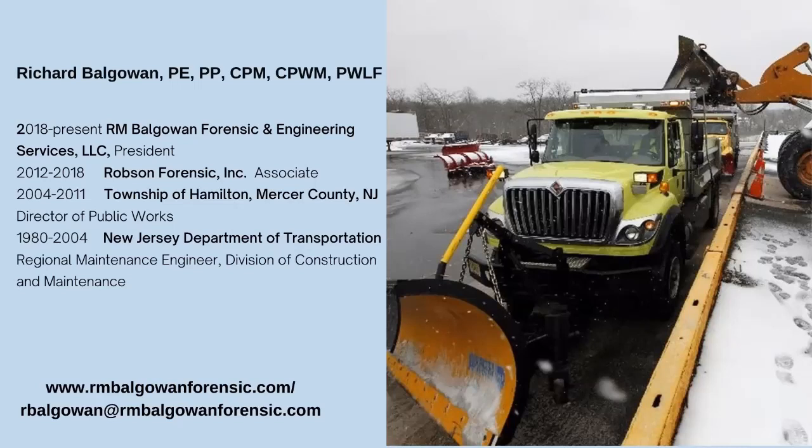So back in the 90s, under the Strategic Highway Research Program, which was being overseen by the Federal Highway Administration, a study was done and a manual was developed. It's called the Manual of Practice for an Effective Anti-Icing Program. And that is broken down into 8 different storm types, everything from sleet to light snow to moderate to heavy snow, etc., freezing rain. And then it gives you the recommended application rates for different temperature ranges depending on that storm type.